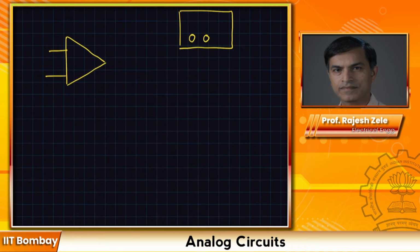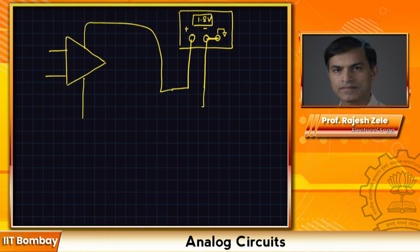Then you will see plus and minus, and then there will be a chassis ground. Typically what we do is we short these two, and on the display you will see 1.8 volts. This is what you will apply to your amplifier.